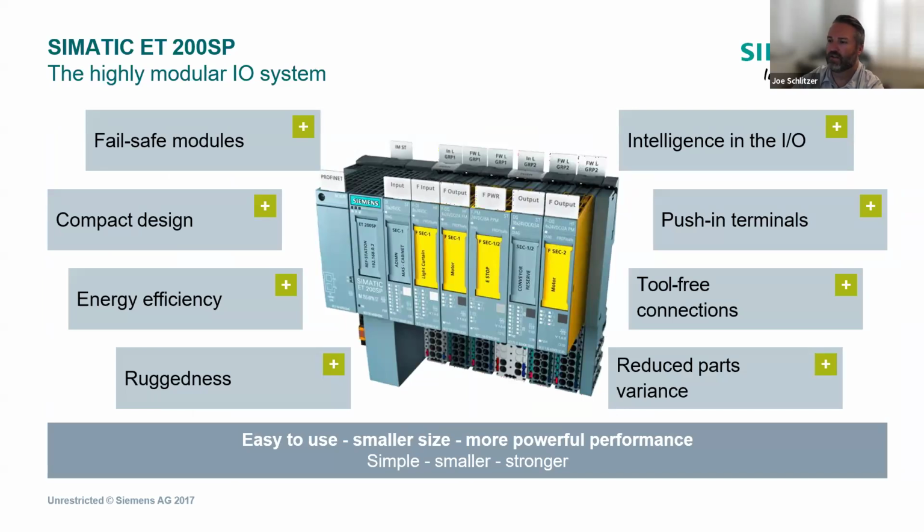And this just gives a brief overview of how it looks. Again, we have our interface module here. Anything that shows up as yellow indicates it's a fail-safe module. As I said before, it's all tool-free. So to push in your wire or wires in the terminal, they're just push-in. You do need to use a screwdriver to press this button to release the wire, but at least you're not dealing with screws. It's a very hardy construction, very energy efficient as well.